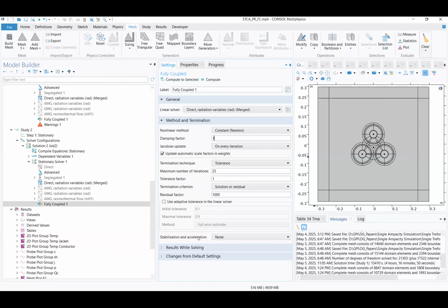And as I showed before, for the electromagnetics 2D generator model, the stabilization is not selected, but it's still available in case you need it. But we are not seeing the electromagnetics, we are still seeing the thermal. Yeah, because I closed it. I see. Before, I demonstrated that the default solver settings used fully coupled, and it had stabilization acceleration not selected, but it was still there, right? It's still an option, you can still choose.